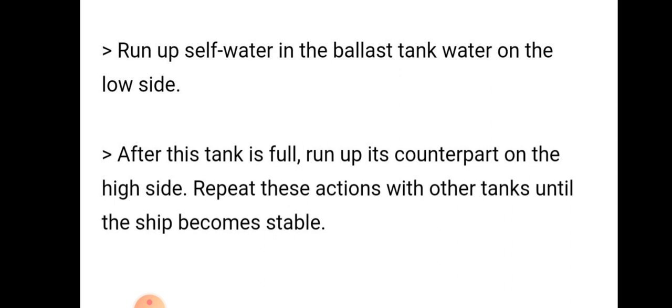Then fill up the ballast tank on the low side. After the tank is full, fill up its counterpart on the high side. Repeat this action with other tanks until the ship becomes stable. These are the corrective actions that we can do during angle of loll.